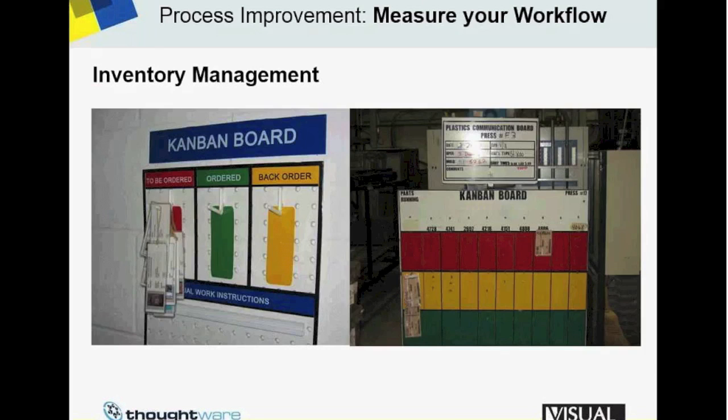Inventory management indicates min and max locations, tells us how to handle materials, and allows us to expose defects through Kanban. The Kanban boards here authorize us to produce and move more parts or assemblies and visually control the flow of products through the process. They set limits on inventory of WIP allowed in the area.